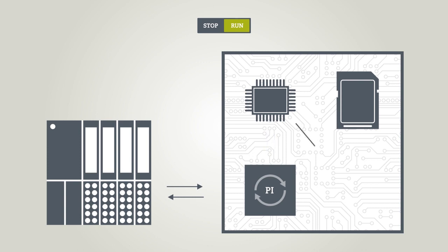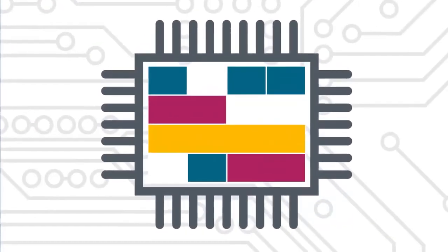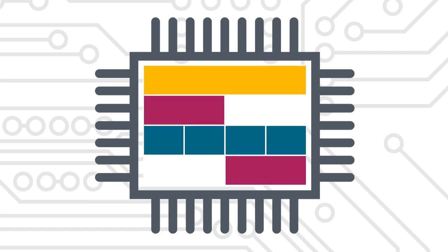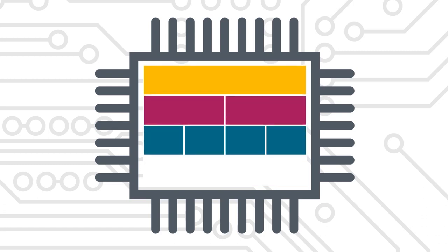Important data is written to the embedded retentive memory when the controller is set to STOP and will be available again at the next startup. You define during programming which data is to be handled as retentive. The Siemens S7-1200 and 1500 controllers have an optimized data filing system. This system significantly reduces memory requirements and access times.